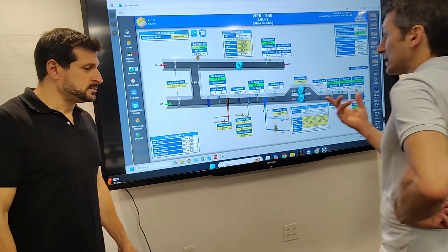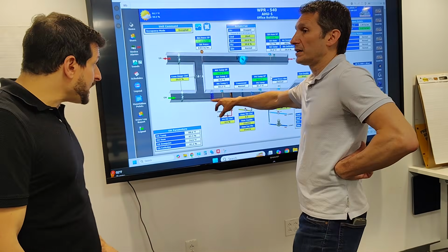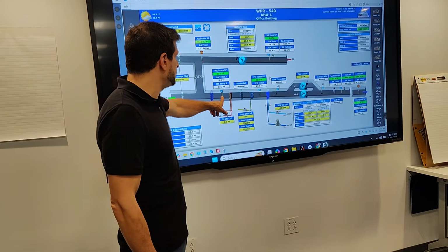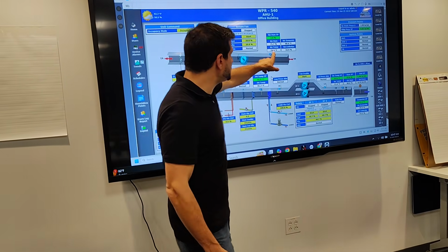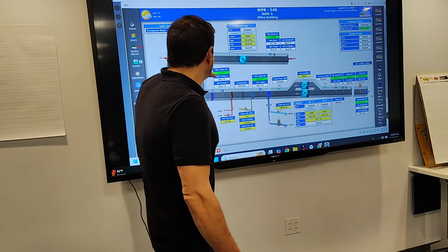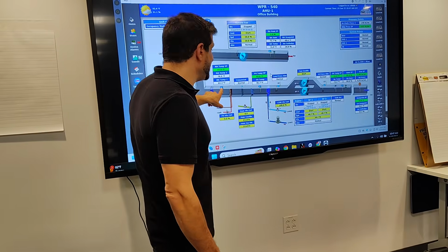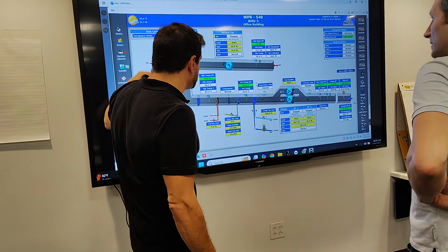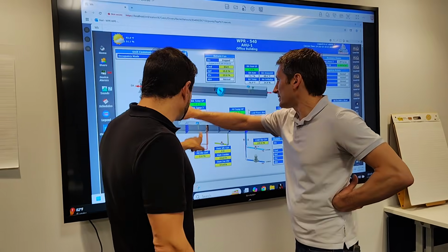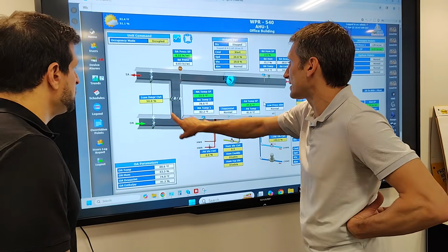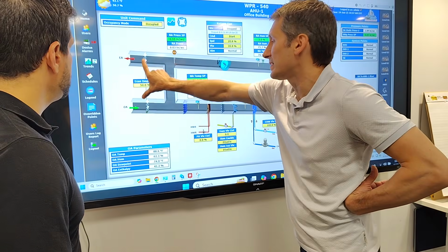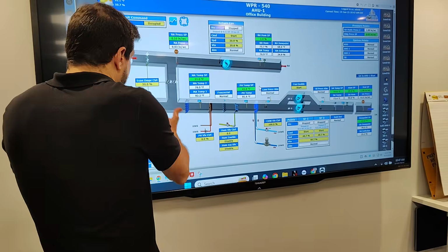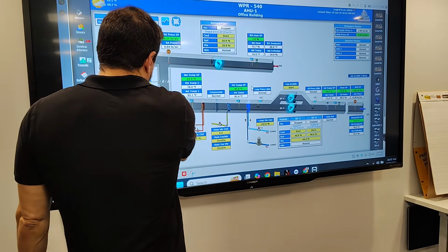Can I go run and look? Because I feel like hot air is coming in. You have 82 degrees in the mixed air plenum. Right? So I have 76 degree return air temperature. So 76 degree return air temperature, 82 here, means that I'm bringing in something hot, and outside I've got 92 degrees. So it's very possible. What I'd like to happen is for this to be cycling in a mix and to minimize this. That's what you have. I mean, it's minimized right now. That's where it's at. It's at that minimum position.